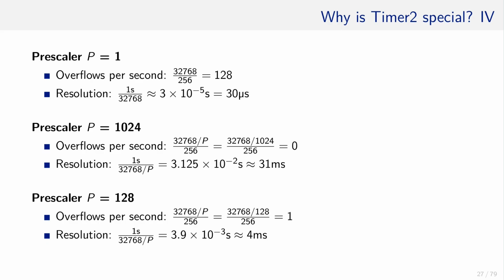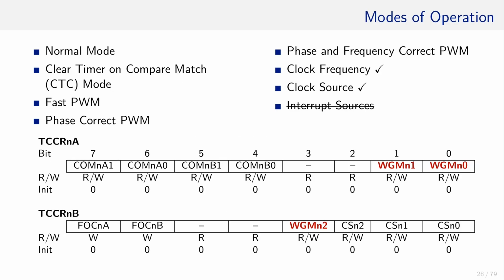That's nice, isn't it? Now we have an accurate notion of time available in our program, and you know how many seconds have passed since the ATmega was powered on. A crystal with a frequency of 32,768 Hz is very inexpensive, and it costs around 50 US cents. In addition, its space and power consumption is very low compared to an external real-time clock. Therefore, it is a very easy way to measure time. That's all regarding the clock signal generation for the timer.